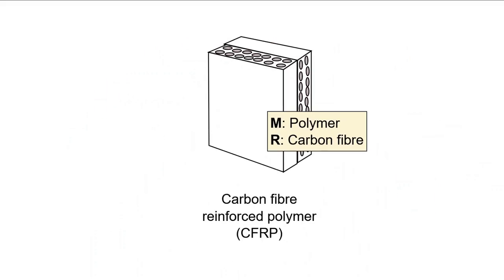When it comes to engineering composites, the one that you're all most familiar with probably is colloquially known as carbon fiber. The correct descriptor for this material is carbon fiber reinforced polymer, and it describes it completely, a thermosetting polymeric matrix which is reinforced by carbon fiber. This carbon fiber is also a polymer, but having properties closer to a ceramic due to being completely made up of covalently bonded networks.